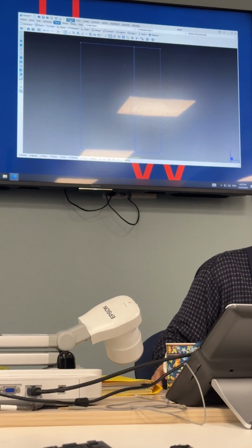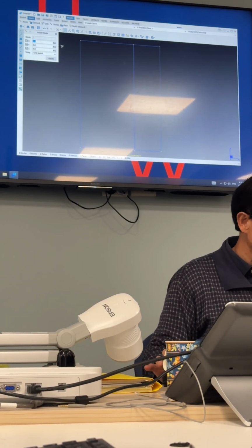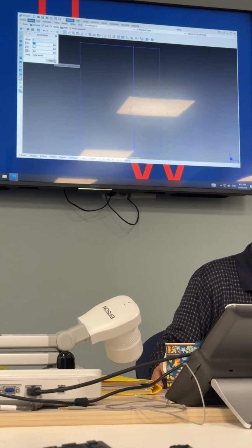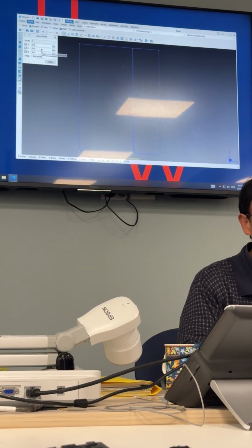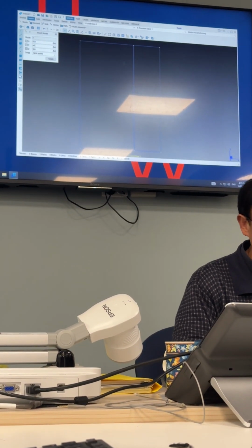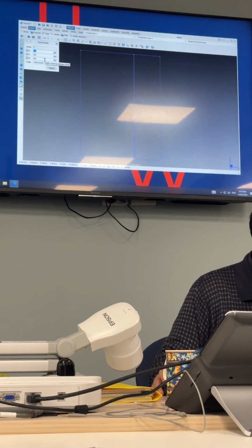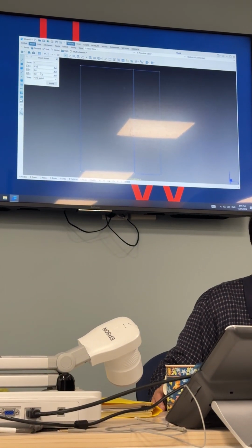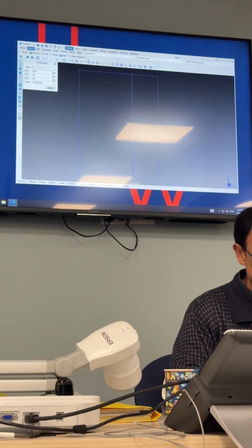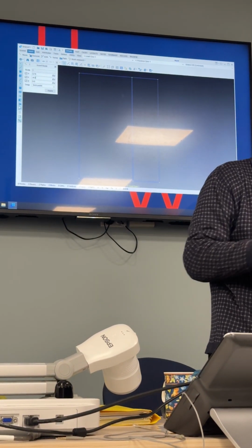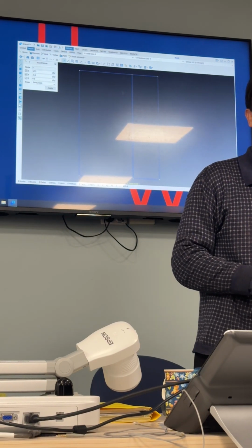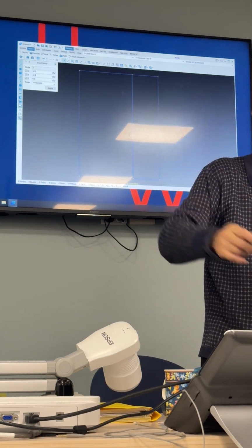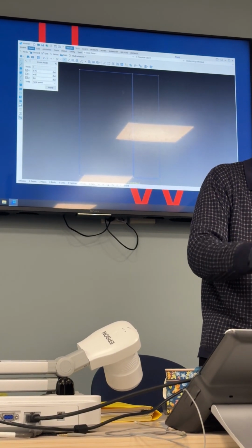Okay? From Visual, Insert, Nodal, you get a nodal point. 3.75, 0, 1. The second point, 0, minus 4.5. And then one more point, 3.75, minus 4.5. Why is it 3.75? Why is it minus 4.5? I calculated this. I want to have this mesh, and I worked out the detail: 7.5, 3.75, minus 4.5.